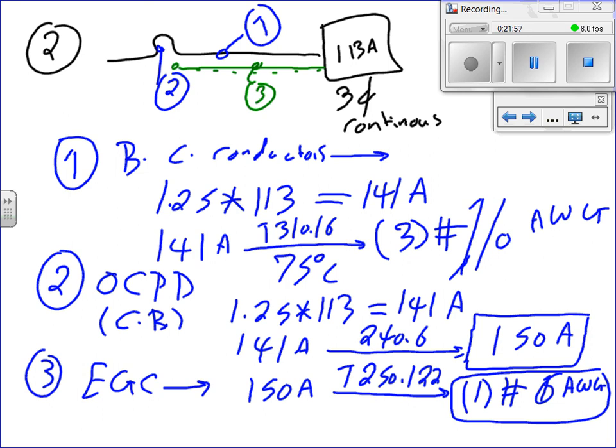Now, the only thing that's missing out of this, Camille, is the voltage. If I tell you this voltage was 208, would it change any of these calculations? No. If I told you this voltage was 240, same. 600, same. 480, the same. So just write yourself a note here. This calculation could be rated for 208, 3-phase, of course, 480, 240, 600, or any voltage in between.